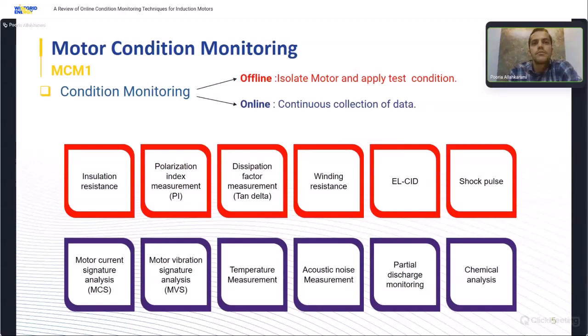However, for high voltage and medium voltage motors, we have a test called partial discharge monitoring. Partial discharges are a localized dielectric breakdown in the insulation system. However, they do not completely bridge the gap between the conductor and the stator core. PD monitoring is especially for medium and high voltage motors, where insulation failure can cause breakdown through the insulation phase. These micro discharges can be detected by online PD monitoring, and the high frequency voltage and current pulses emitted are measured, providing a leading indicator of insulation degradation.